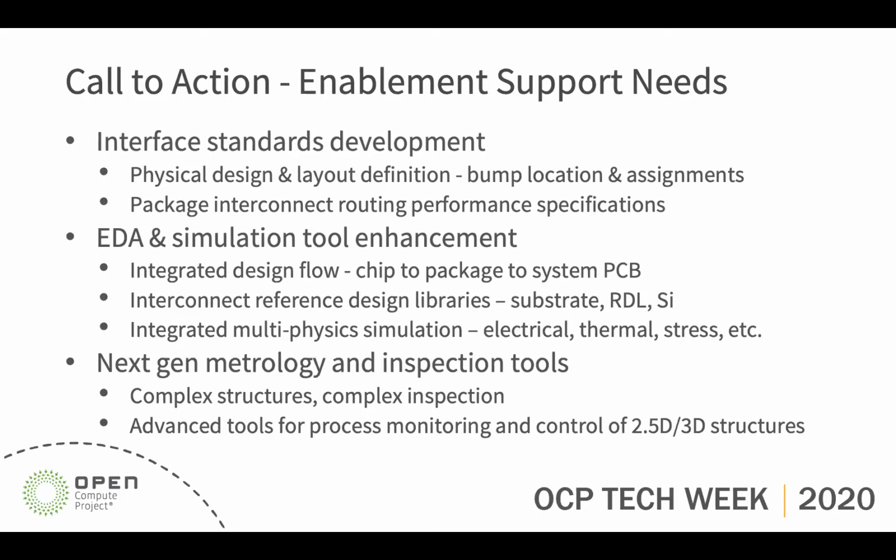And as the industry moves to partition virtual SoCs, a portion of the interconnect design complexity that was previously dealt with at the chip level has now been moved into the package. So to avoid complex custom and extended design and simulation cycles, there's a significant need for the development of interface layout standards, design rules, reference designs, and guidelines to facilitate this process.